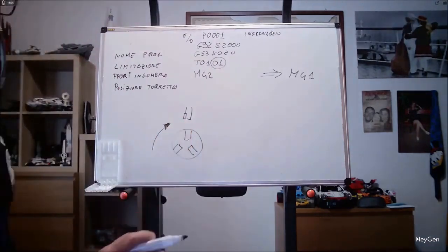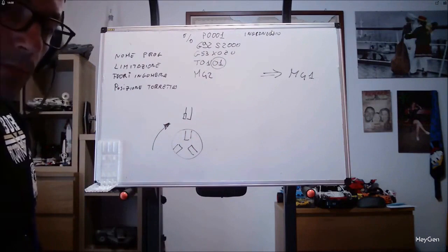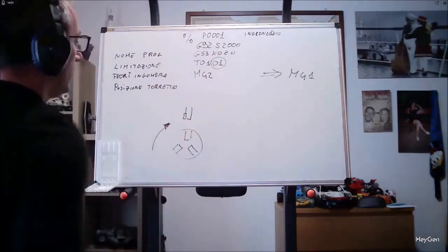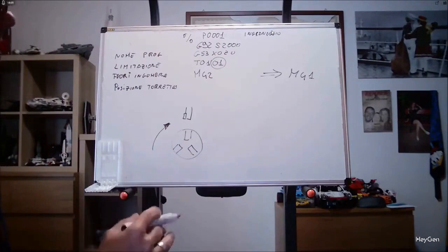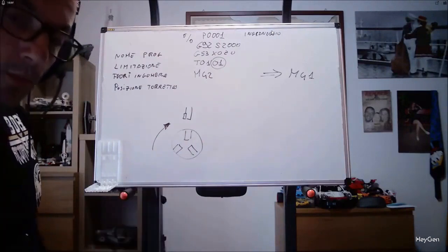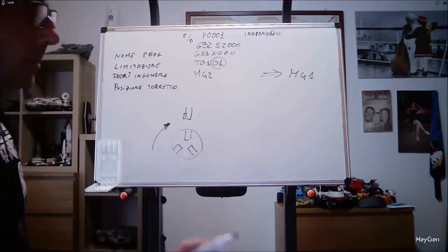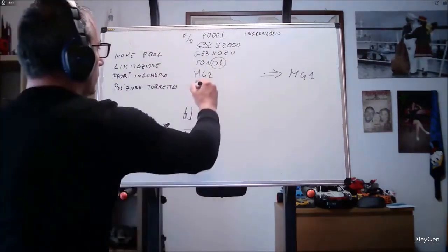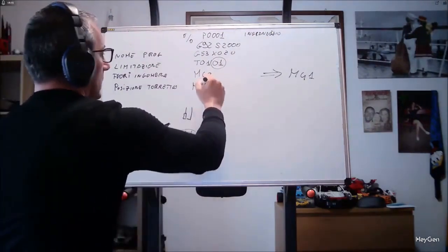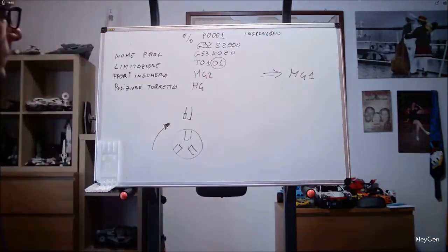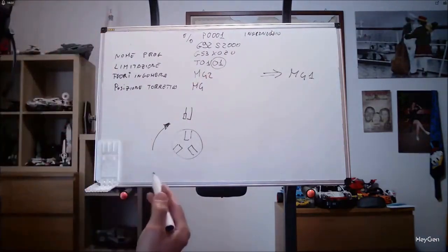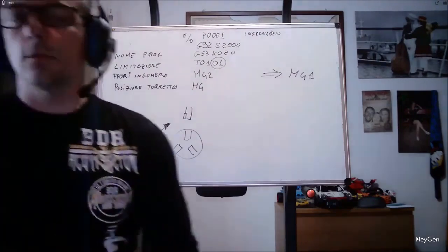This doesn't apply to all lathes because the Italians work in reverse, but for Fanuc, Siemens, or Okuma, the rotation sense, the M4 rotation sense, is clockwise when looking at the turret.